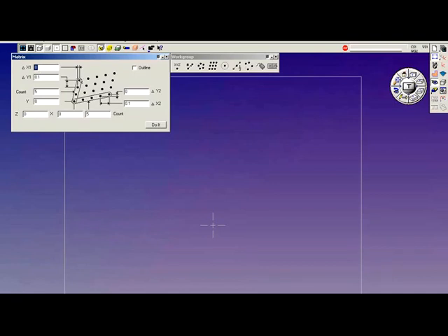If we wanted this row of holes to be at an angle, we would type in a value here, and each hole would incrementally move from the previous hole in the positive or the negative direction as specified here. Delta y1, if we follow the arrows from the dialog, determines the center distance point to point along the y-axis. The count along the y-axis determines the number of holes.